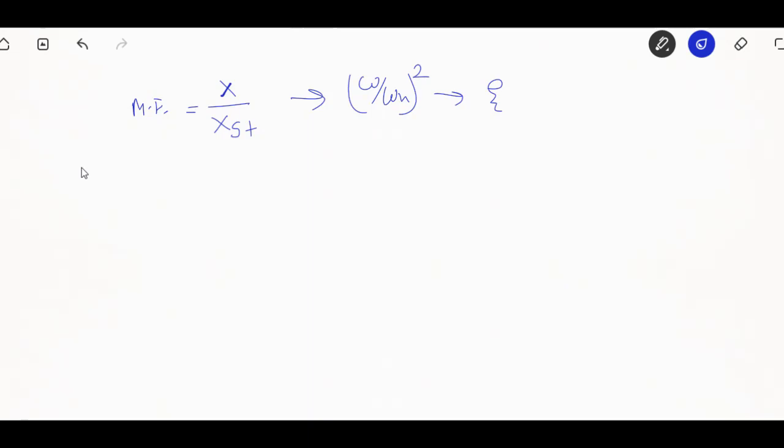So this curve that I drew in the last lecture will help show how the resonance condition can be avoided, and what the value of amplitude is, keeping that frequency ratio in mind. Now we will talk about a practical case which we analyze again. Our interest is just to calculate the magnitude of the vibration under the operating condition, and how we can resolve it and bring the vibration level down to a normal operating condition, in which we can avoid failure, right?